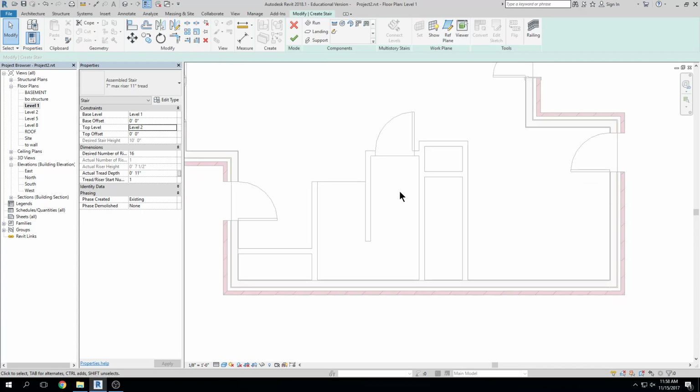You have to be pretty methodical about stairs because if you don't do them right, you're finding out they don't work, right? The way that we're going to draw our stairs, we draw them separately in this case. There is what's called a multi-story tool in Revit where you can draw stairs that are identical from floor to floor. They are used in an application where you have like a high-rise, right? Those multi-story stairs work when your floor plates are exactly the same distance apart, right? So in the case where you have 2 or 3 stories where the floor plates aren't the exact same distance apart, you're going to do separate stairways from each level. So from main level to upper level, and then from main level to lower level, you'll do 2 separate sets of stairs.